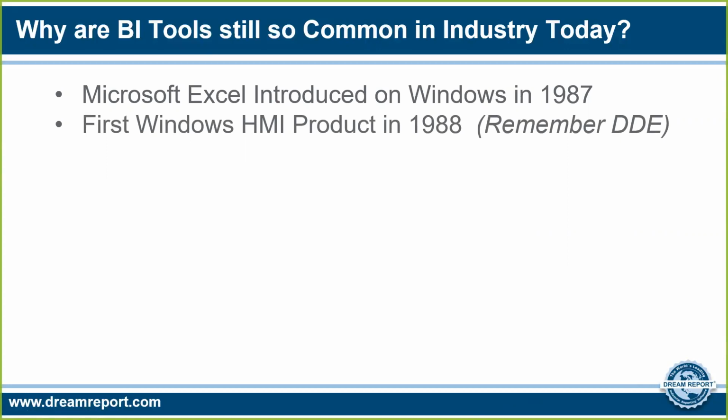Many of us who were working with HMIs back in those earlier days probably remember taking DDE pokes and taking values from our InTouch tags and poking them into an Excel spreadsheet. And we were so excited to have a report, if you will, in Excel versus just a dump of raw data, which was really all that was possible before then in flat files out of our PLCs or HMIs.